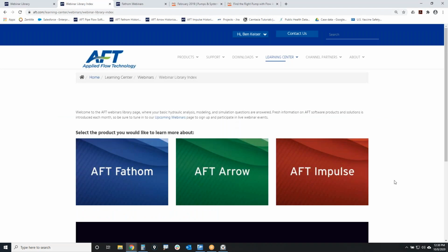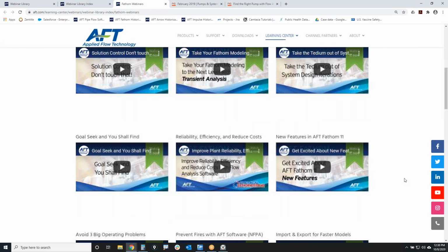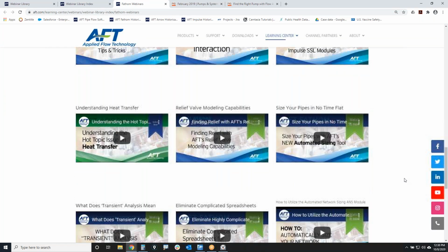So once you get into our webinar library, you can go into the AFT Fathom webinars, and if you scroll down a bit, there's a webinar called Size Your Pipes in No Time Flat. In that particular webinar, I go into really good detail on how you would be able to size a piping network if you do not have any cost information. So that's where you are minimizing the overall piping weight of your system.